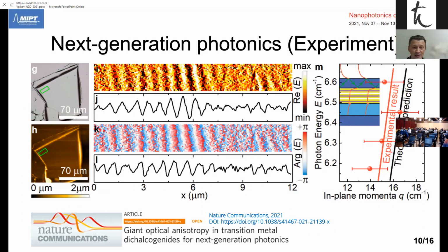Here one should probably mention that MoS2 as an anisotropic material yields significantly better light confinement, even in comparison with artificial anisotropic metamaterials. And this, of course, opens a new concept of vertically integrated photonic circuits, which has recently been proven to be a useful degree of freedom for efficient nanoscale light manipulation.